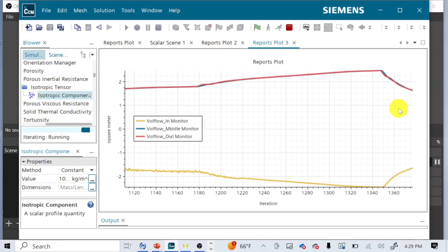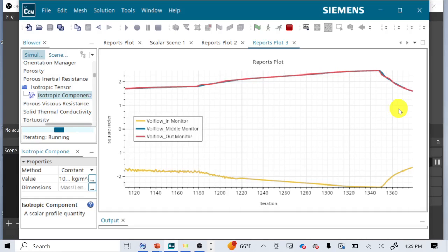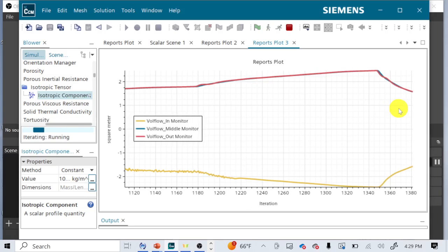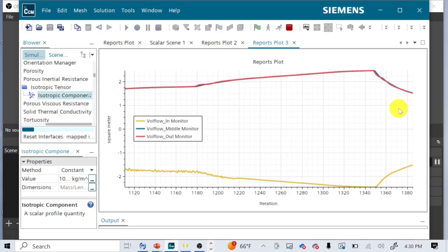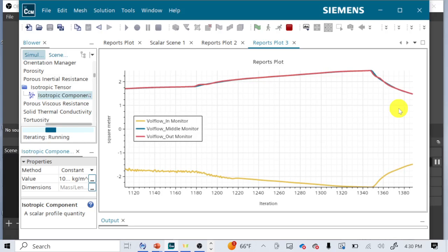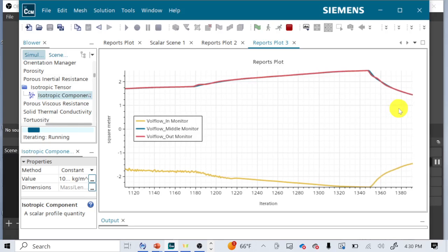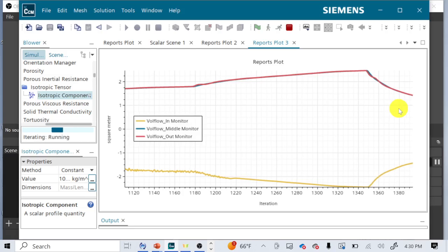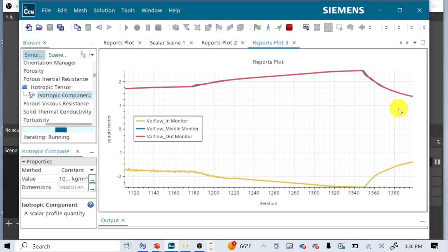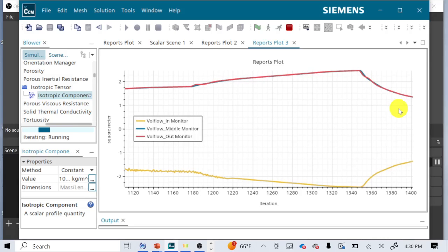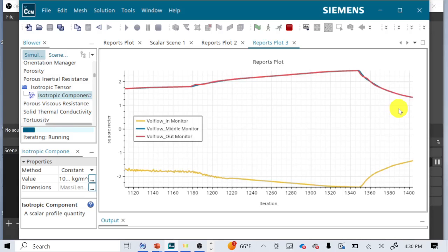Also, incidentally, why is one of these negative? It's going in versus out. Because if you take this dot product, which way is the area facing? Well, the answer is it depends. It always faces to the outside of whatever region you have selected. Always. Because you have an inlet on one side and an outlet on the other side, you can't make them entirely consistent. So one of these is always going to be negative, at least. You might have two of them negative, one of them positive. But there will be some amount of opposite signs going on here because just based on this dot product, it will compute a negative value for at least one of them.